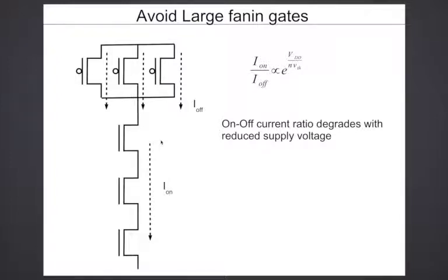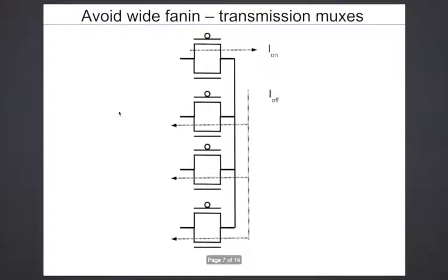So it might be okay for certain cases perhaps. You have to look at it on a case-by-case basis, where you really want a very high fan-in structure, but you don't want to have this problem. So perhaps you could think of limiting the pull-up currents and trying to solve this particular imbalance problem. So what people do is avoid large fan-in gates in the standard cells used for sub-threshold operation.